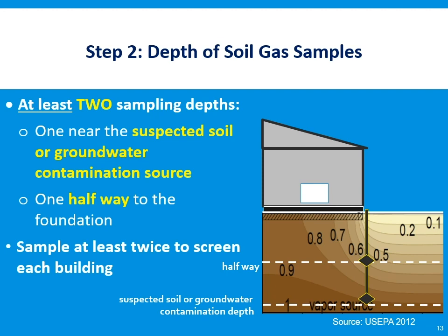As shown by the figure, which is taken from modeling conducted by US EPA, the shallower depth of the soil gas probe yields concentrations that are not indicative of the concentrations under the foundation. However, the deeper depth on the soil gas probe, pursuant to the figure, produces contaminant concentrations that are similar to those under the foundation.